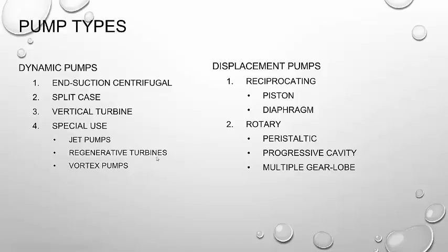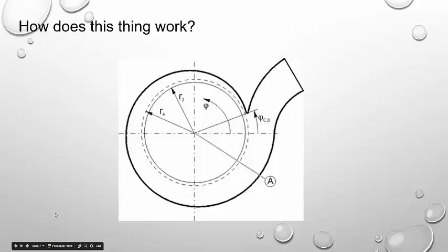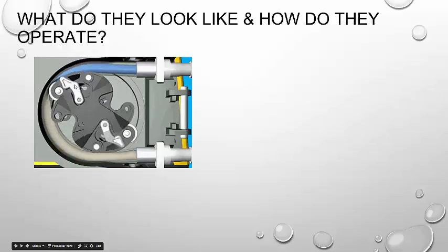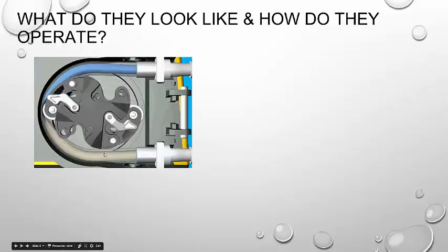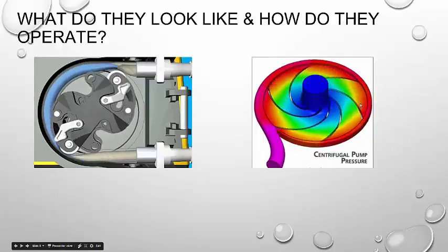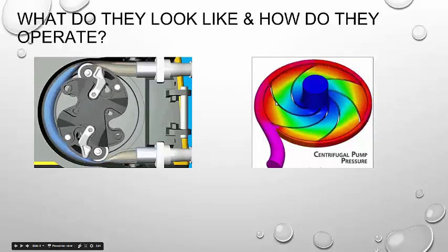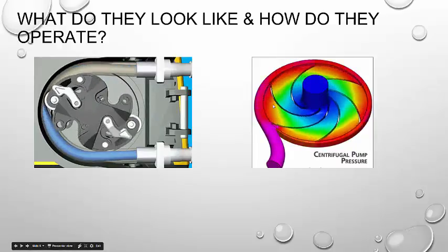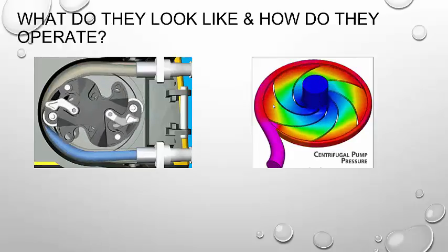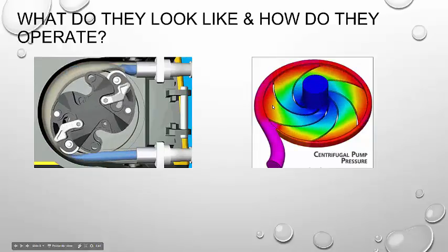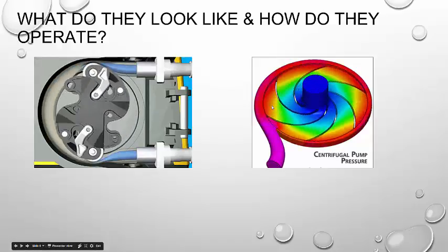Okay, so let me kind of go back so that makes sense, because there's some of you that are interested in going into the environmental side of things, and I want you to make sure you understand this. Okay, so if I look at this displacement pump here, you notice that I can draw water through this tube without introducing air. This thing will degas very quickly because it's rotating very quickly. The energy is applied rapidly. So if I'm interested in analyzing things like volatile organic carbons, which many of them are carcinogenic, things like pesticides and various things which will volatilize, they'll evaporate.